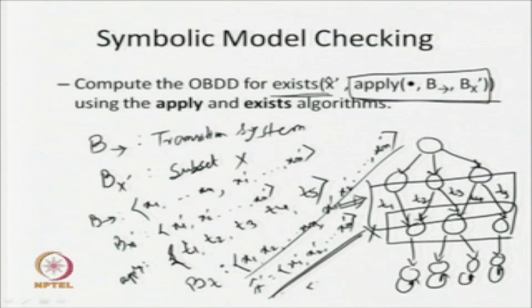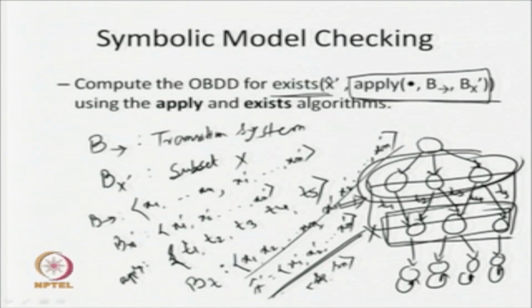So, this is basically the representation from present state to next state. Now, we are making it independent of those next state variables. It had all the variables, and now we are making it independent of the next state variables. So, in the resultant final BDD, it is independent of next state variables. Eventually, we are getting the representation of those particular states only. Just try to visualize it and understand it: we are getting these particular states only, represented by the present state variables.